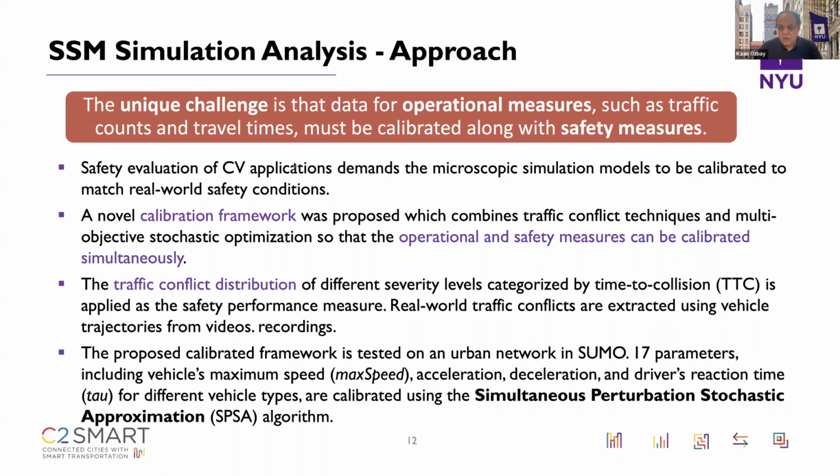We are also able to get real-world traffic conflicts from vehicle trajectories, from videos, recordings, and so on. We use that real-world data and the TTCs derived from it to calibrate our simulated model. So the model is not only replicating travel times and volumes correctly, but it's also replicating the interaction between vehicles in terms of vehicle trajectories.